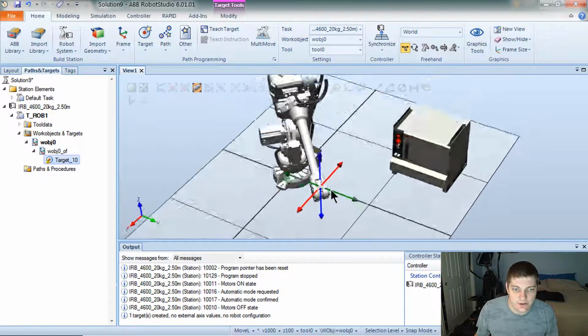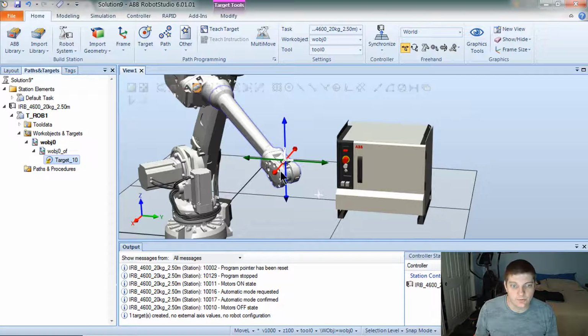But we've only defined 3 degrees of freedom here. We've defined X, Y, and Z, but we have not defined the roll, pitch, and yaw of the system. So let me use something a little easier. If this roll of tape is a point in space, we've got Z-axis, X-axis, Y-axis towards the camera and further away, and then we have roll, which would be this direction, pitch, which would be this direction, and yaw, which would be around its own axis here.